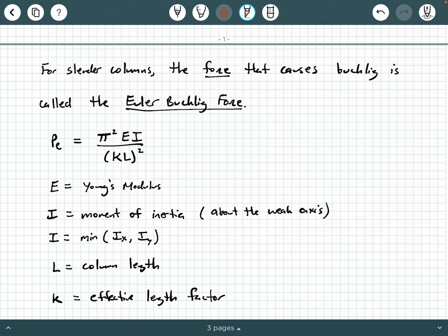Why is that? Well, if you double L, if you say instead you have 2L here, you're squaring that term, right? So the doubling of L gets squared. It becomes 4 times, or a factor of 4 difference of P sub E. So I may have said it backwards a second ago. P sub E will decrease by a factor of 4, okay?